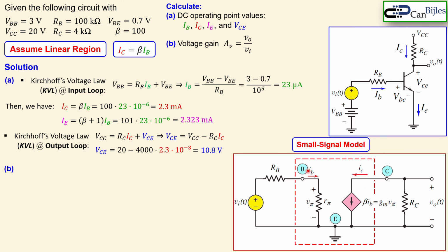You see the base, the collector, and the emitter nodes. So this dashed red box is only that transistor, and outside we see the RB and also the AC sources. So everything in the DC domain is disabled. That's why you also see this RC from the collector node to the DC voltage VCC going to ground, because this node is now grounded in the AC domain. So everything is grounded here. Now we also measure the voltage between this node, the collector, and ground.